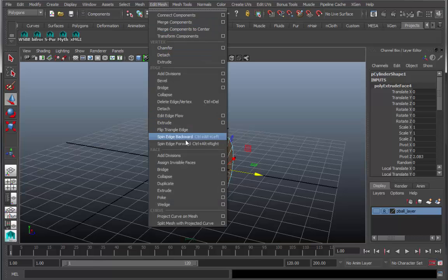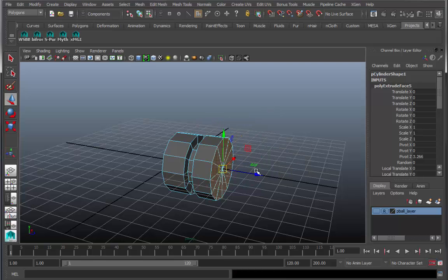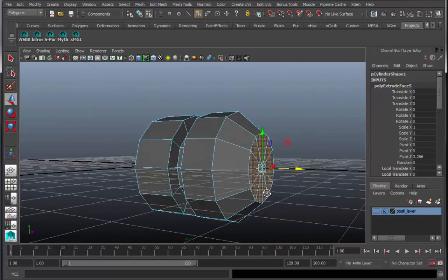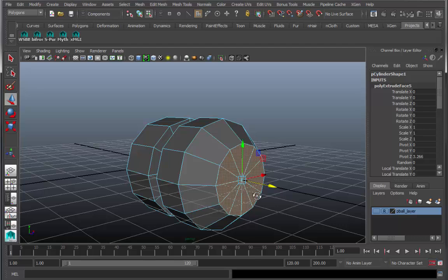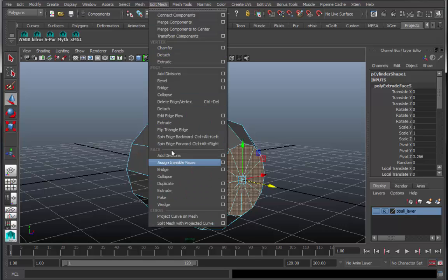And I want to extrude again, and this is going to be a combination of extrusion out first, and then I'm going to pop immediately to the scale tool and scale it down, creating this kind of strange little doorknob. I'm going to push it in again. This bevel, as it were. And that's a combination of both extrusion and scaling, translation after the extrusion and then scaling. And I'm going to do it one more time.